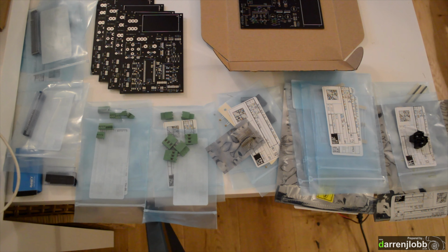So the way we're going to hopefully do this is hydraulically. There's two ways you can go about it really. You can either have a steering motor, which essentially bolts next to the steering wheel and just turns the steering wheel, so you don't really have to interfere with the tractor at all. I'd like to try and integrate this completely hydraulically, so it's completely seamless in the background, nothing in the cab.